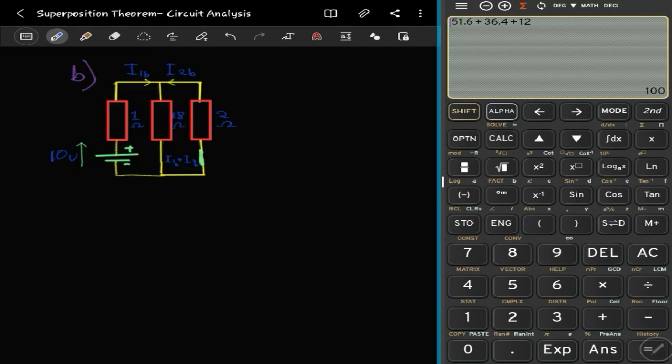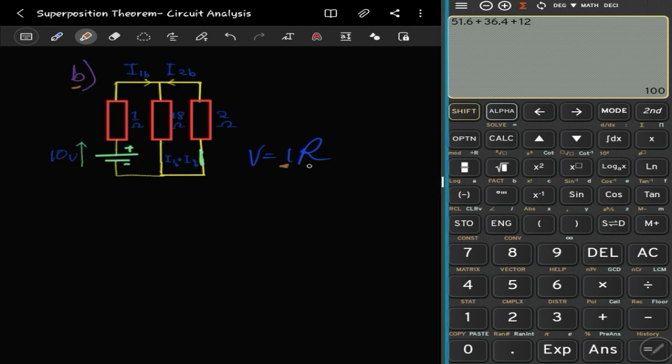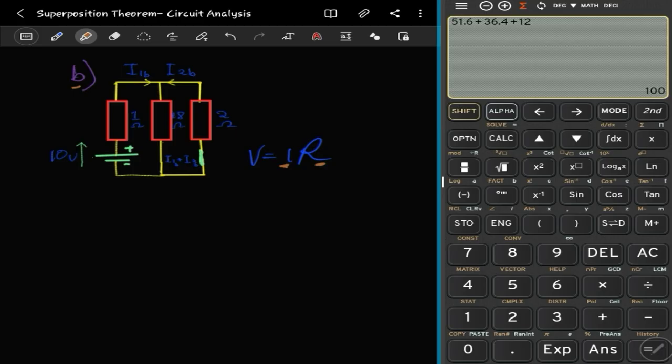So far, per all our discussion, one of the commonest things in applied electricity is that we use this equation, which we are very well aware of, right? And right now, our aim is to find what part of the current, which is this I2 here, right? And with this, we'll be able to find what we're actually looking for, the I1 plus I2, right? So before we find I2 in this section B here, we'll need R, right? V is very clear. In this particular case, V is just this 10 volts here, right? So we'll go on and try to find the R.